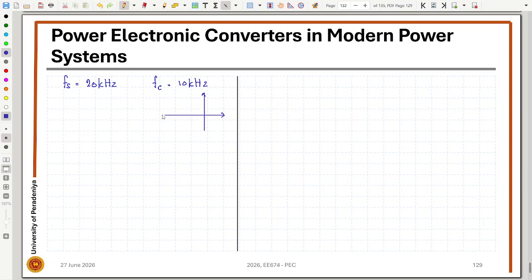So we will assume the two pole locations P1 and P2, and take the pole location plot. On the frequency axis we have Fs, Fc, then Fp1 and Fp2. So this is 20 kilohertz, this is 10 kilohertz. I will select Fp1 as 1/10 of Fc, and we will select Fp2 as Fp1 divided by 4. So this is kept like this.